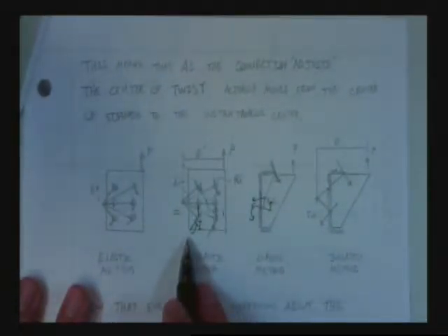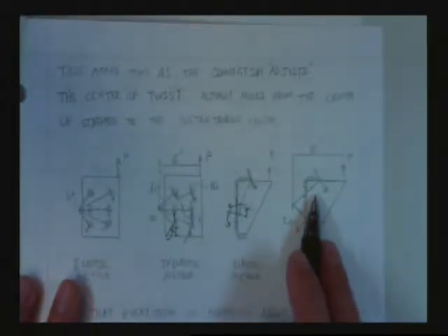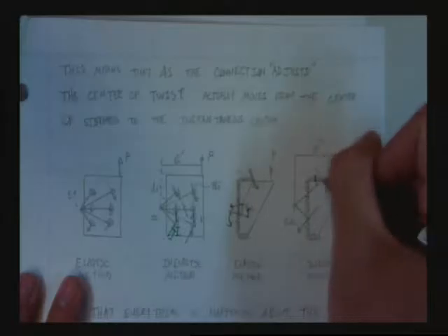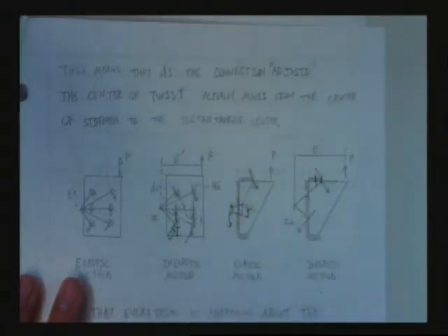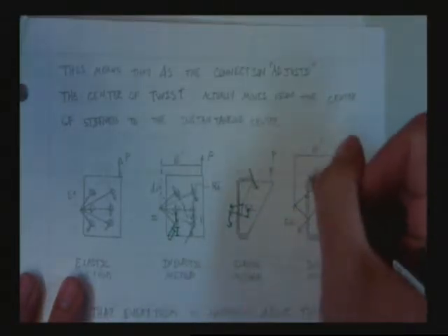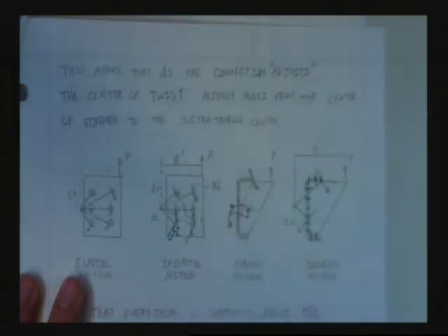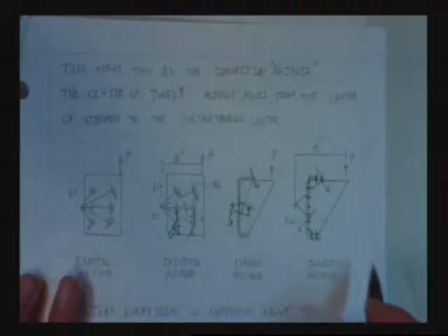I think it's much easier to think of bolts first to introduce the concept, to make sure you understand it. But you could think of these welds as individual bolts that are 1 inch or 1 unit long. Imagine just a whole bunch of bolts side by side by side together. It's another way to think of it. And what's it going to do? It's another way to think about welds.